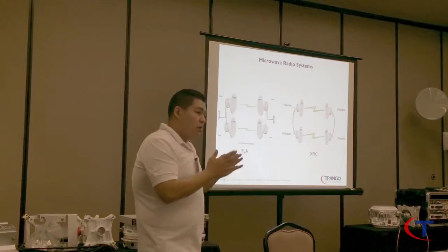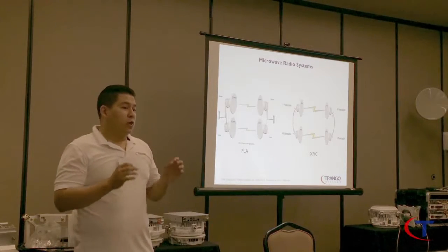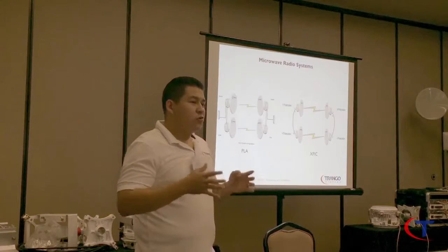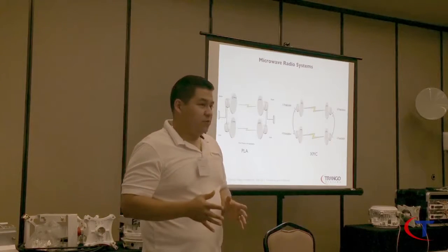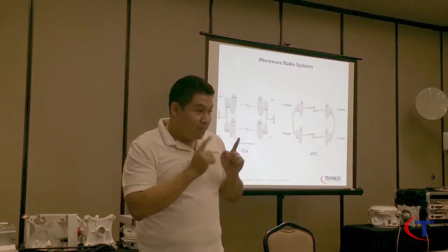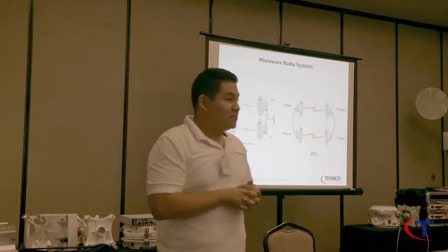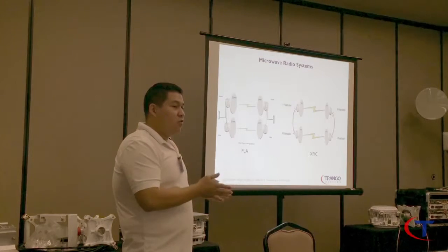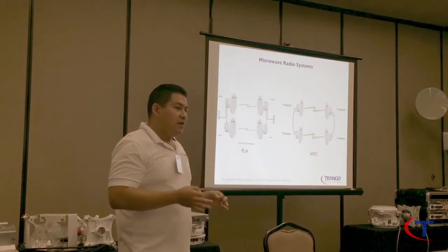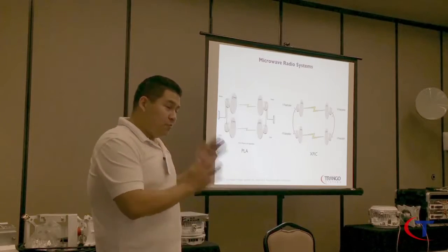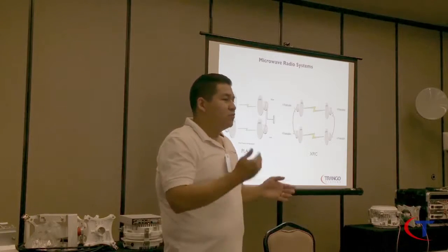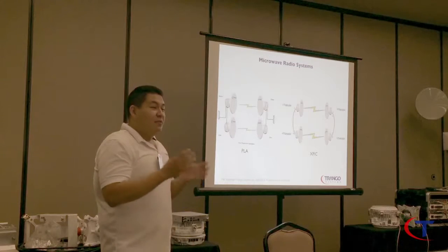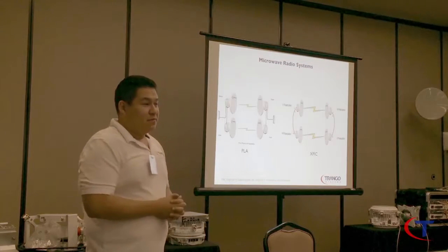Now, when we talk about 1+0 and 2+0 systems, we got to remember something. When we talk about 2+0 systems, we always recommend using out-of-band management. Okay? If you use in-band management, you're going to get management conflicts. So, our best way of doing this, you can do 2+0 PLA that must be done with OBM. On 2+0, you can have 2+0, 3+0, 4+0, as much as your wallet can afford. The management is always going to be independent. Okay?